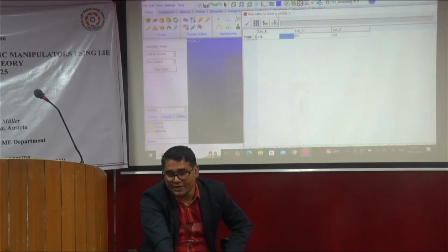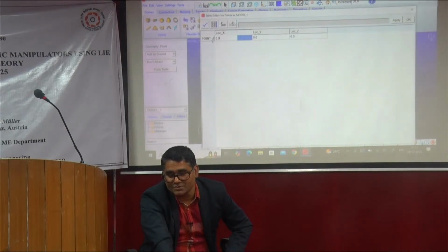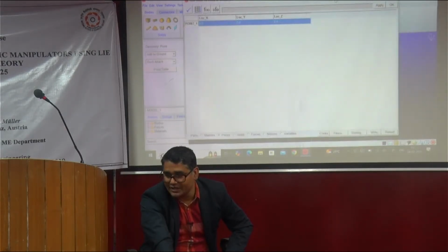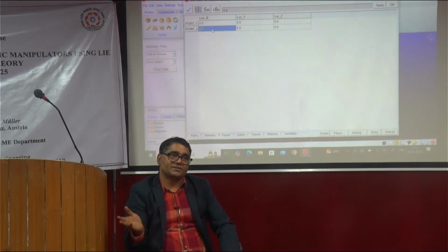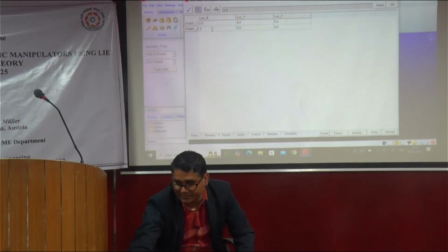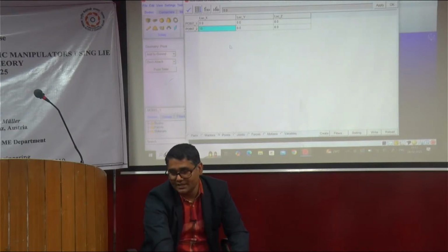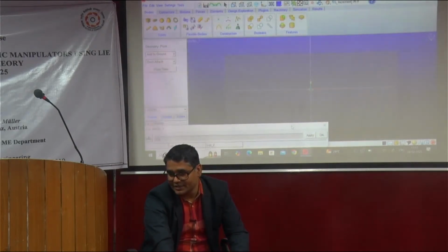you will find point 1, point 2, point 3. So suppose this point 1 is 1, 1, 1. Now the second point, if you want to create, you can go here and create. Okay, so suppose in the x direction it is 10. Okay, so now you can just apply it and you can see it is created.